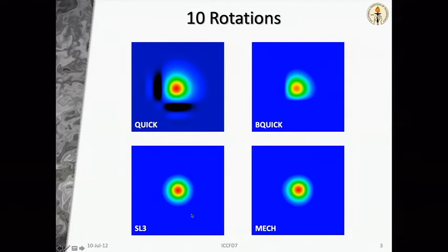Even if you put in physical diffusion, these errors don't go away. They might be more difficult to see because diffusion smears out everything, so it will smear out these errors. These are exactly the numerical errors we've talked about. Remember, when we approximate derivatives, there are some terms that are missing, an order delta x squared term or an order delta x cubed term. Those missing terms are exactly what causes these sort of errors. So these are numerical errors.